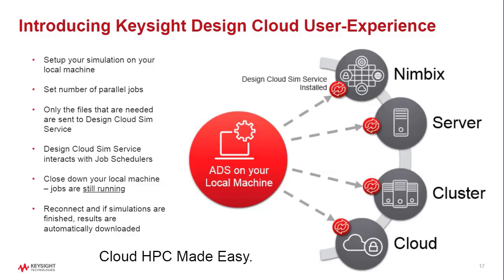The beauty of this is that now your actual local machine is decoupled from the simulation. I can shut down my PC, I can shut down ADS, it doesn't matter, the job is still running. And I can always check on how the job's going by looking at a web service, which Dan is going to show you a little bit later on. The next thing is that the moment I start up ADS again, it will reconnect to the sim service, check if anything's finished and ready to be downloaded, and then it will download those files back to my local machine.